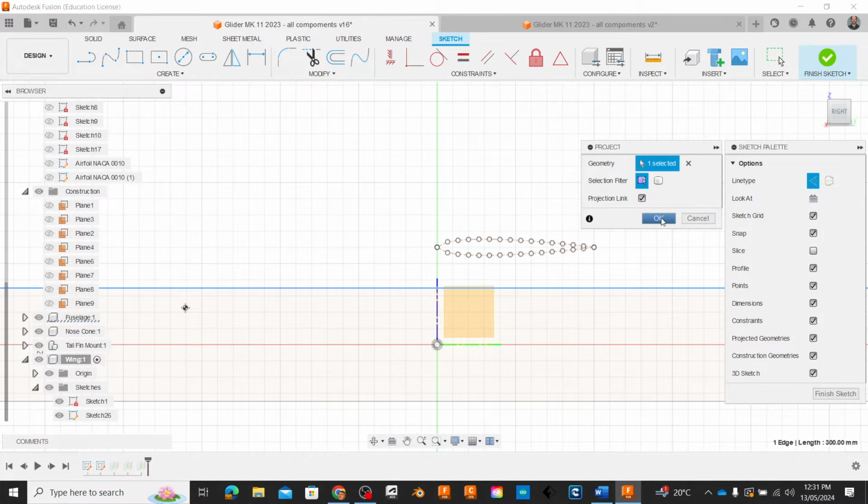So 110 down the bottom and 30. That's the maximum profile, the maximum size that your wings can take in the Z and Y dimensions. The X dimension is 300, as we've gone over before. Okay, so we'll click that in place. Now this wing has to fit inside this construction box.